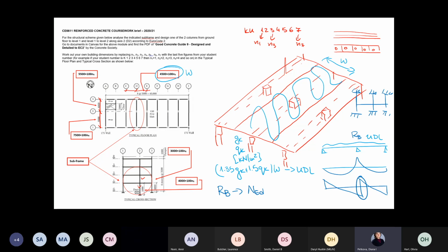In terms of steps, it's really calculating your slenderness, calculating the limiting slenderness, finding the classification of your column or the category, stocky or slender, stocky really, and then using the M and N and the corresponding charts, 9A, B, C, D, and E. You then will calculate the required area of the reinforcement. If it so happens that you don't have a value for the As, then you add the minimum percentage of the reinforcement. This could happen because in this analysis we see that the moments are relatively small, but then again you might have quite an interesting load in your columns.